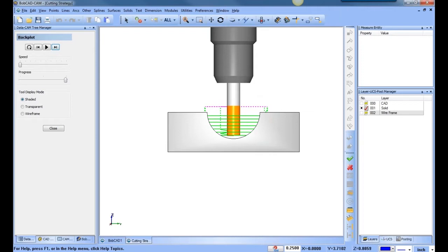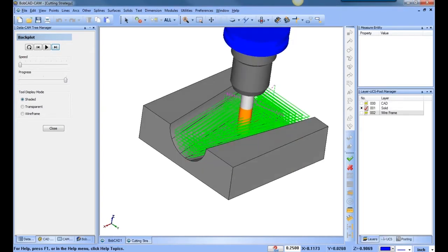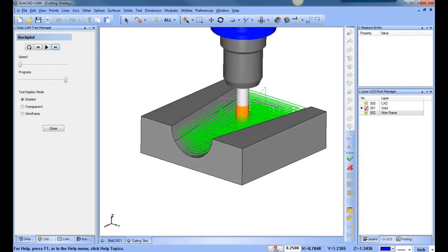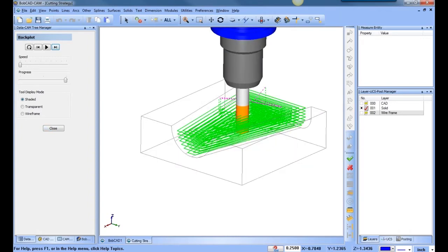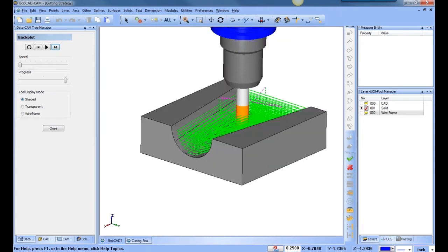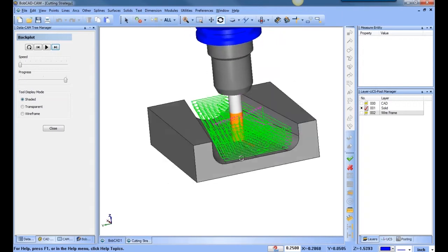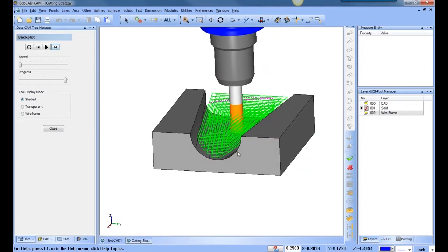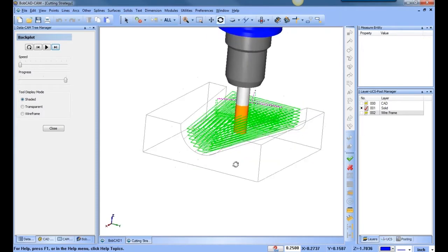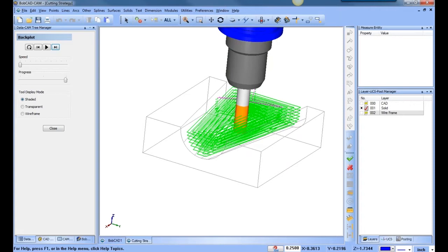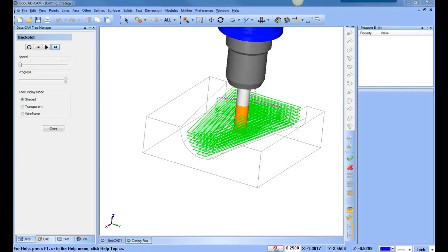Okay, great question just came in from Brian. Brian asked, how am I toggling between the wireframe? Okay, there are some hotkeys that you're going to want to get to know, get familiar with. One of them is S for surfaces. It's really important that when you're generating your toolpath, that you check to see, has it gone where you think it's going to cut? And if the surfaces are shaded, you can't see where that toolpath is. Did it go around or through that surface? So if you click S on your keyboard, you can toggle the shading on and off of the surfaces so you can see exactly what's going on. So that's a great tip there, Brian. Thank you for asking. Hopefully that answered that question for you.